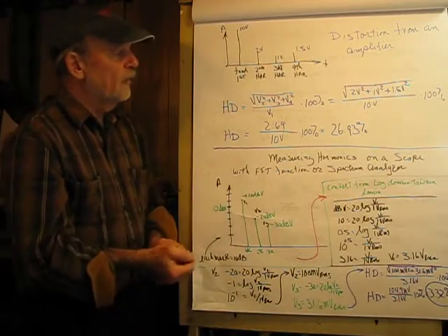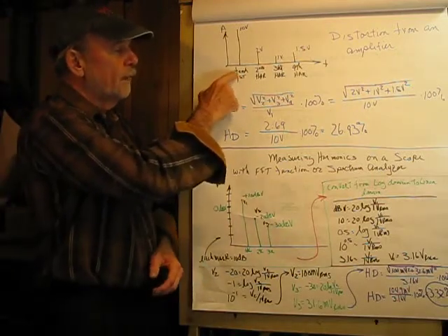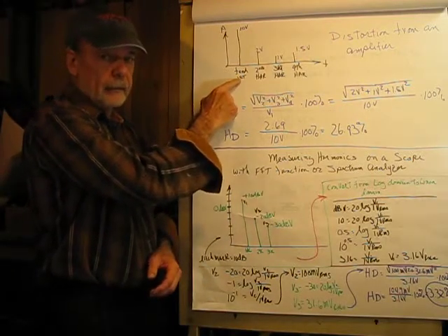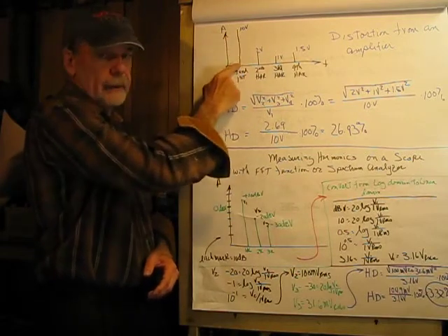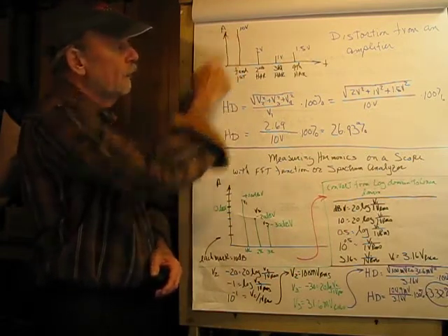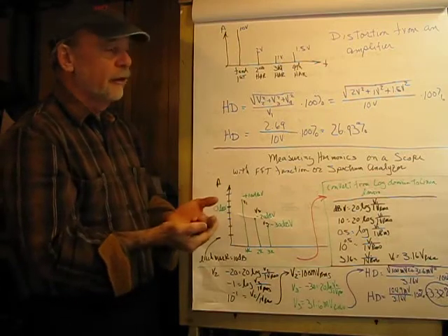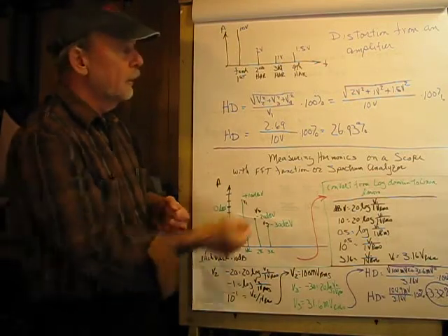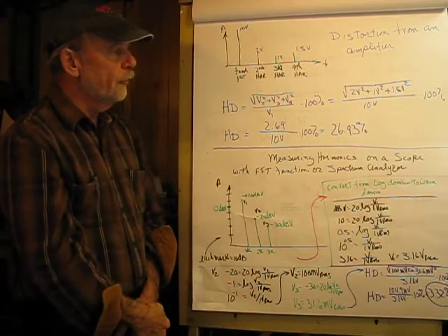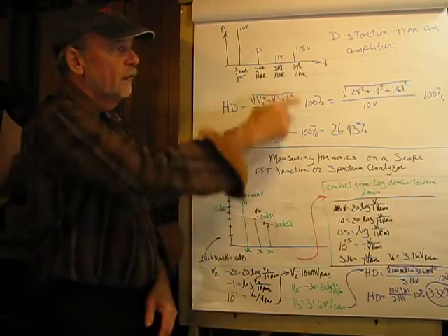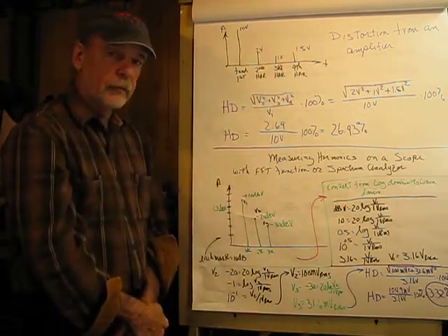So suppose I have an amplifier here, and my fundamental or first harmonic, now this is the guy that we want, is 10 volts, and it's kind of nonlinear. We have some distortion present. Second harmonic is 2 volts, third harmonic is 1 volt, and the fourth harmonic is 1.5 volts.